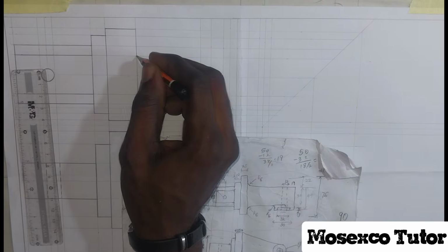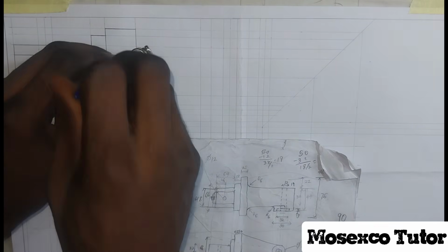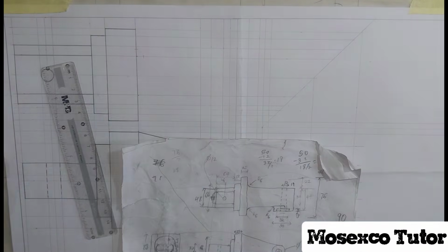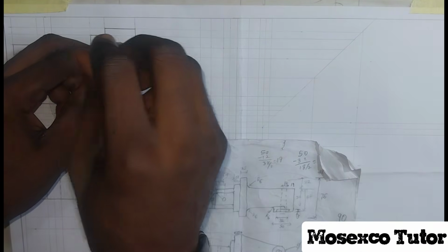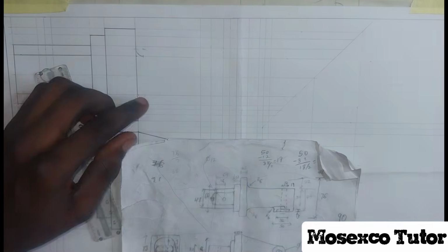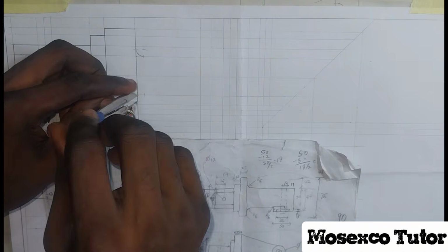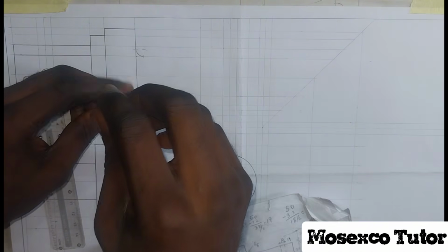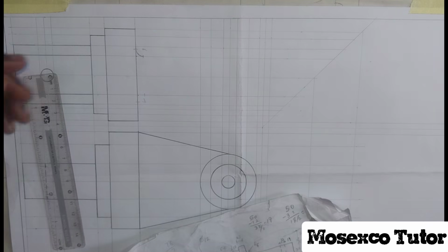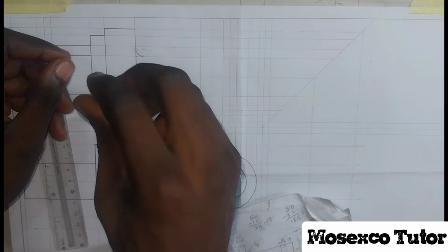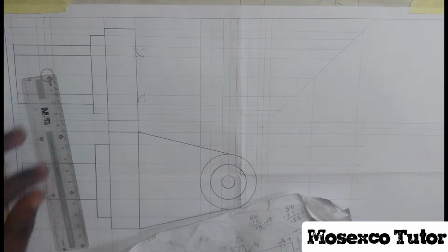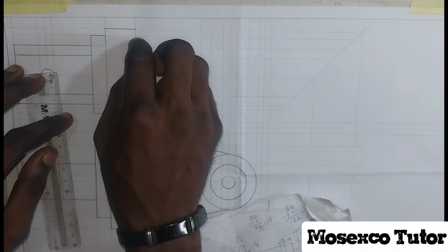Going to the plan, I started with this same line that we have there from those 2 points. I take my compass, radius of 0.6 to get arc. So I mark the 2 intersections there, then I mark another arc from those 2 intersections, then from that point I get the arc that joins them together. First thing is to put it at the points, get 2 intersections to the lines that make the points. Now where the 2 arcs are meeting, put it at the first point, get an arc, second point, get an arc. Now the two new arcs, you put it there again to get the arc that intersects with them.